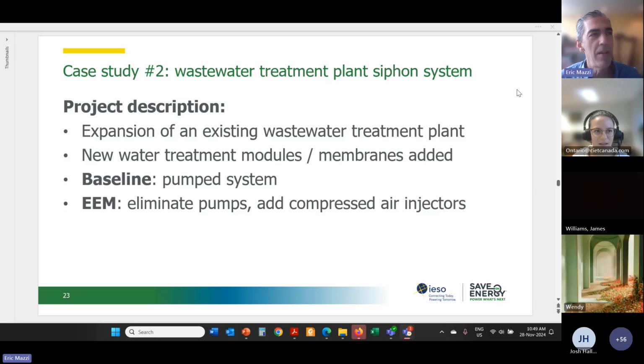So why not submeter and monitor all loads, especially for baseline data? That's a question by someone, Z3. You could do that. That comes back to a judgment call. How much of the process loads are you going to meter in the as-built system? You could submeter all loads, but keep in mind, case study number 3 coming up is for a natural gas processing plant.